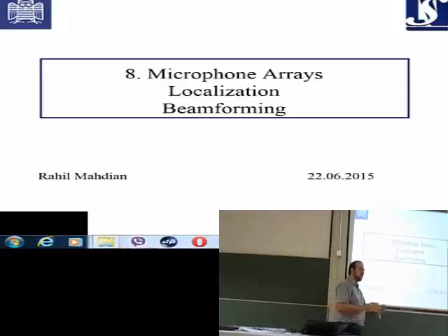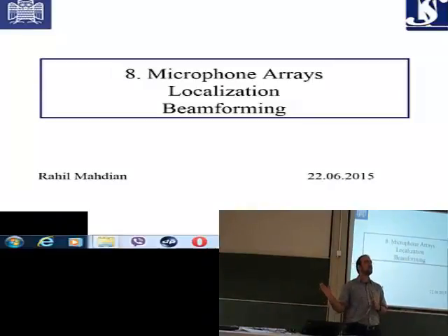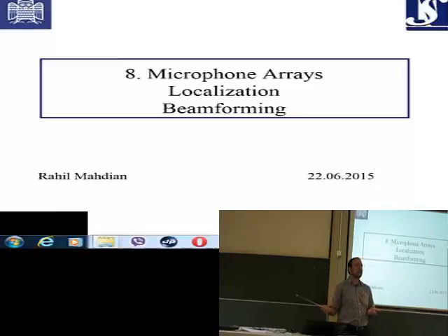So the difference between the filter bank, wavelet, and joint time frequency resolutions like the STFT and Gabor is that for filter banks and wavelets, we can have dynamic tiling of the time frequency plane, whereas for the STFT or Gabor, we have just a constant tiling of the time frequency plane.